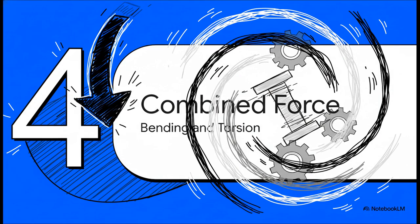Now let's put it all together in Section 4, Combined Bending and Torsion. Because analyzing combined forces in the real world is incredibly complex, engineers rely on something called equivalent moments. On the left, we have the equivalent twisting moment, or TE. This relies on the maximum shear stress theory. It essentially defines a single imaginary twisting moment that would produce the exact same maximum shear stress as all the actual combined loads. It equals the square root of M squared plus T squared.